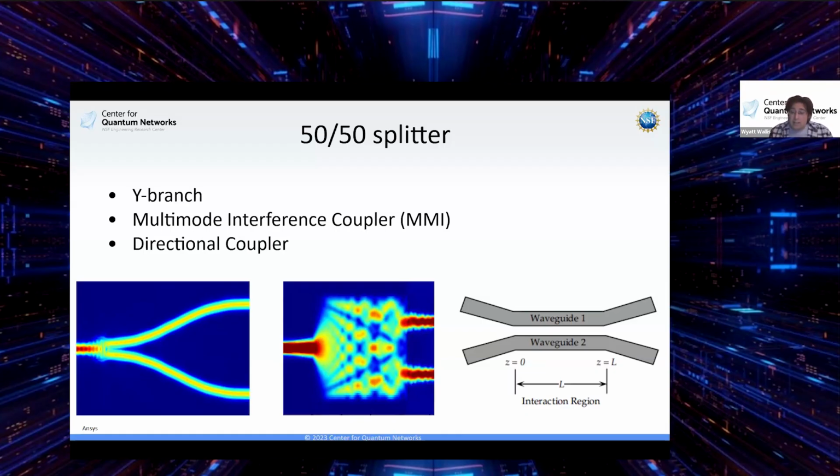And the reason why we want these waveguides to pull away from each other and be far enough apart is because sometimes you don't want what's called evanescent coupling. Evanescent coupling is this idea of the mode profiles. If we remember in Shelby's part earlier, she had those diagrams with the mode profiles, and you could see there were the little tails trailing off on each side of the boundaries from the waveguide.